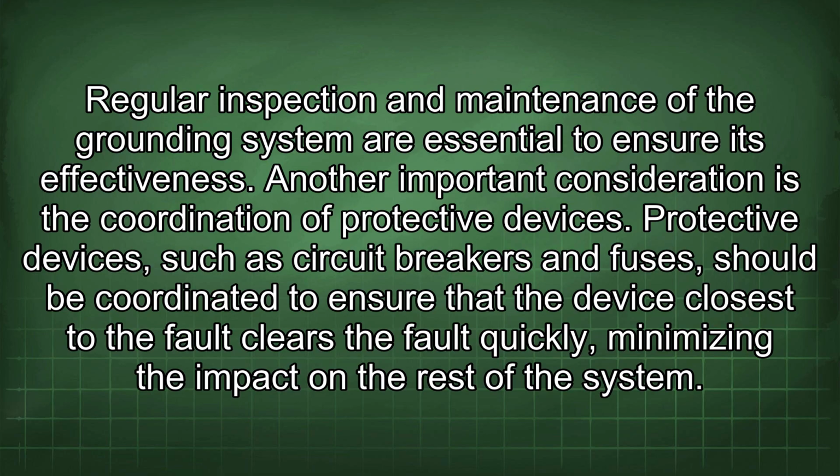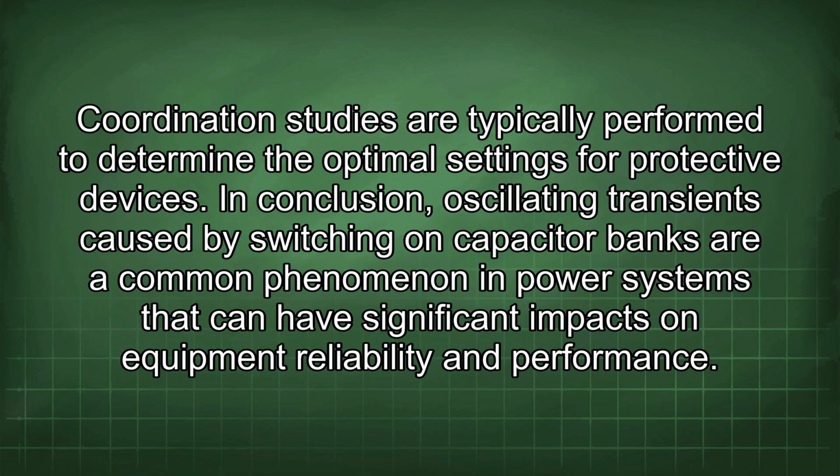Another important consideration is the coordination of protective devices. Protective devices, such as circuit breakers and fuses, should be coordinated to ensure that the device closest to the fault clears the fault quickly, minimizing the impact on the rest of the system. Coordination studies are typically performed to determine the optimal settings for protective devices.